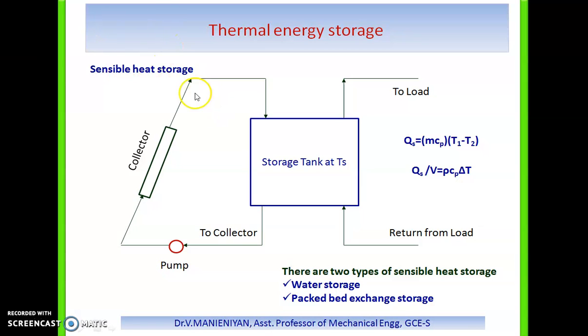So first we discuss the sensible heat storage system. Sensible heat storage involves a material that undergoes no change in phase over the temperature range encountered in the storage process. Some of the basic equations for a thermal storage system: Q equals m Cp delta T.